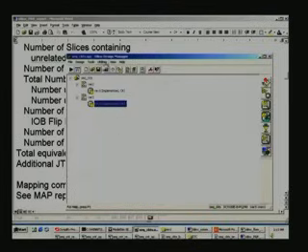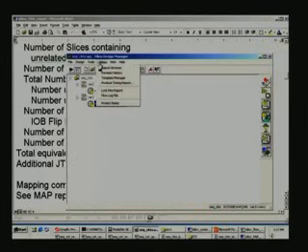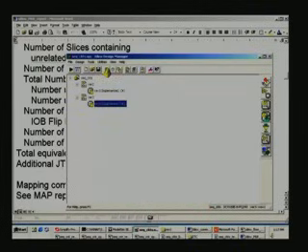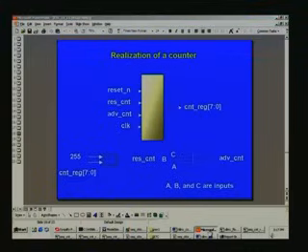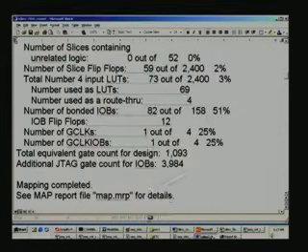From here we can see there is what is called utilities and a report browser there. If you click on this, you can get the report even after you closed it after running the place and route earlier, and you can click one after another and inspect all these reports, or we have already copied this log file here.